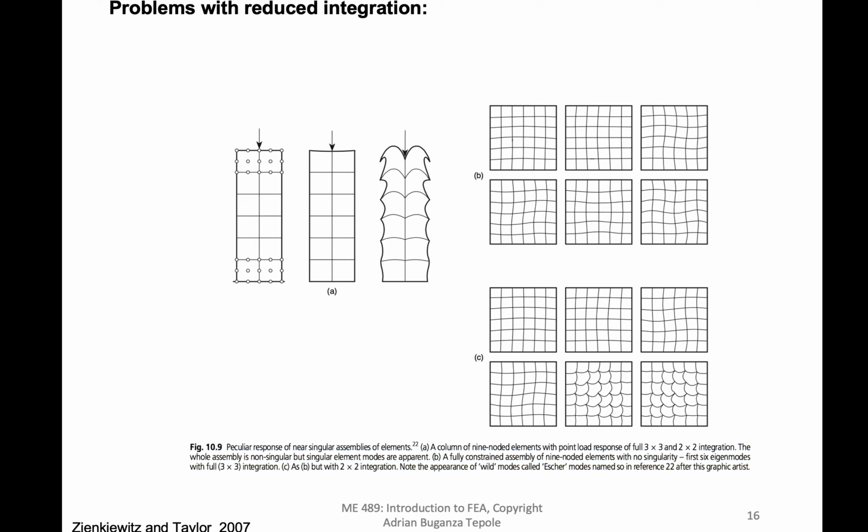Also here, there are always some issues with having point forces. As I said, point forces lead to singular stress distributions. So that's another thing that you have to be careful about. But if you see this type of pattern of deformation in the mesh, then you should be thinking, oh, this looks like some instability, some oscillation. Maybe there is some zero energy mode in my solution due to the reduced integration.